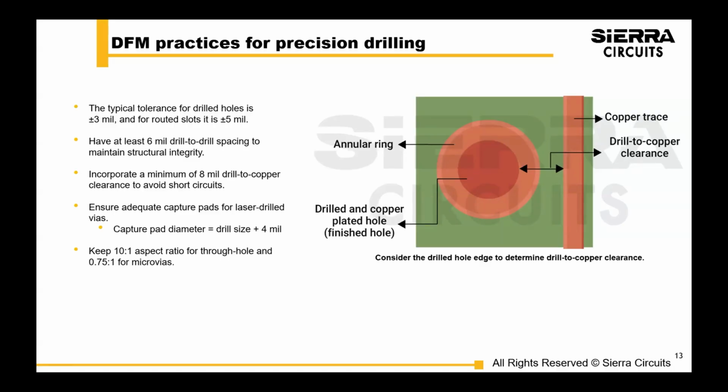And to make sure that you're following, again, the right pad stacks for that material, for that class of product, class 2 versus class 3 is different, and for your fabricator. How well can your fabricator hold certain tolerances?